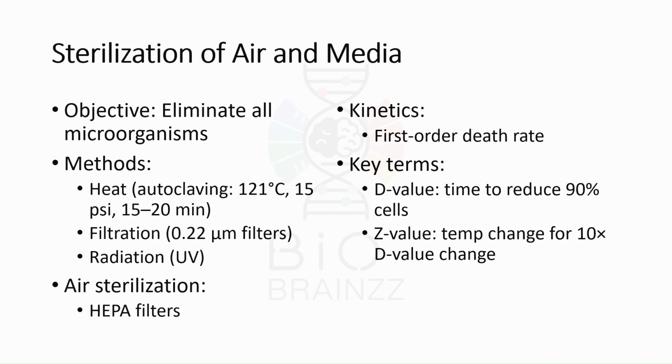Sterilization of air and media. Sterilization is done to remove all microorganisms and avoid contamination. This is very important because contamination can spoil the entire process. Common methods include heat sterilization, filtration, and radiation. Important terms like D value and Z value help in understanding how microorganisms respond to heat.